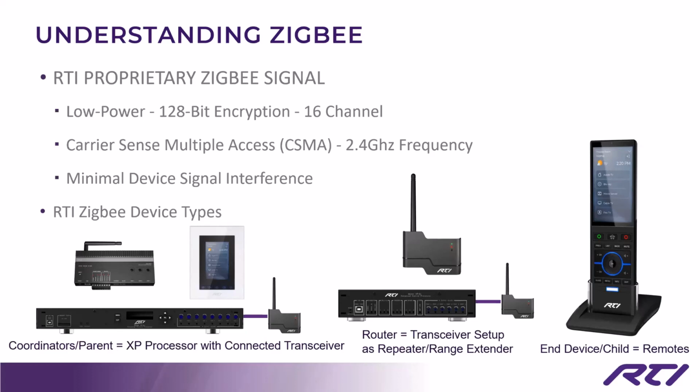The Zigbee routers can typically be a ZM24, which is set up as a repeater and range extender, but you can also utilize a processor as an expansion processor with that connected ZM24 transceiver as a range extender as well. So just keep that in mind. You do have those options.